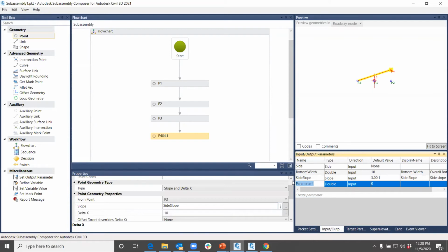And this width is going to be whatever the width is that we want it to go on our side slope. So we could do side slope width, which is just the computer side. We're going to want it to be a number. Let's go with 6 to make this thing 2 feet deep. And for our end user, we're going to tell them side slope offset. Side slope offset will be the description that they will see when they hover over it.